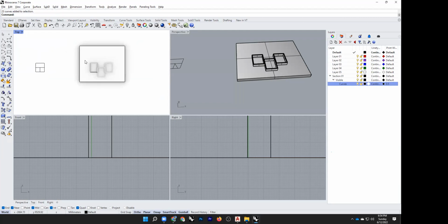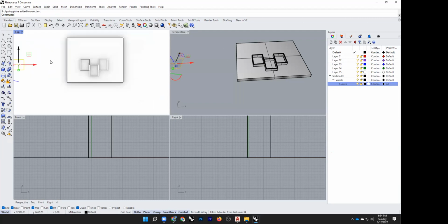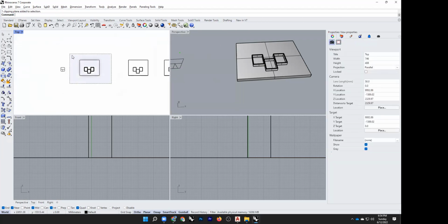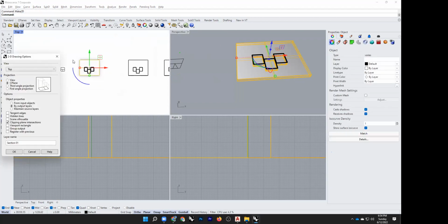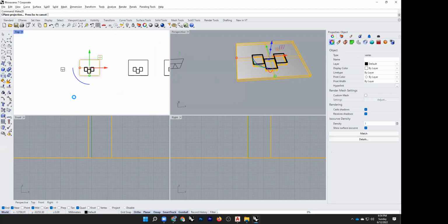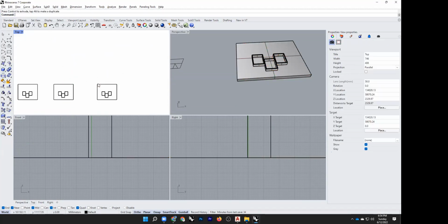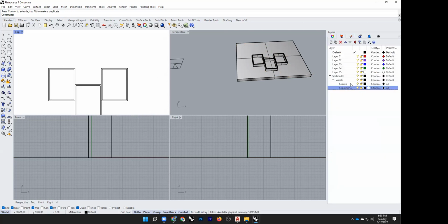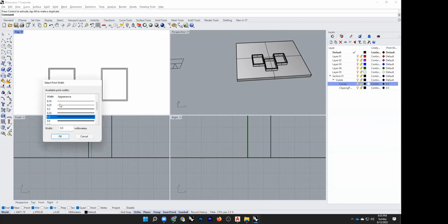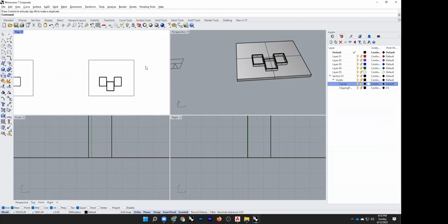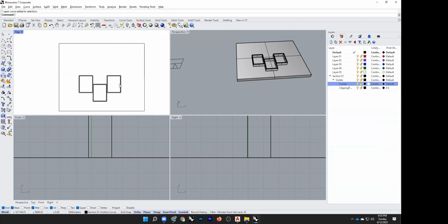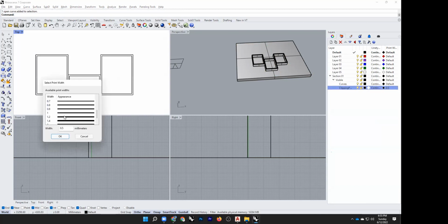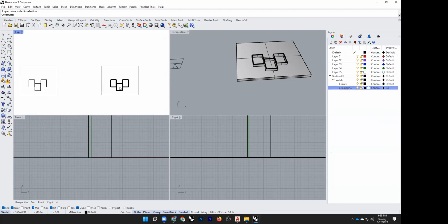So what I was saying is I need to select this and turn this in top view. Now it's cut in plan. Now, if I do the make 2D and do the same, you can see I have 2 layers. One is clipping and another is just curve. So if I make this curve default, you can see our normal lines will be single line and cut lines will be thick as it should be in the drawings. So I can make this even thicker. Only the cut things.